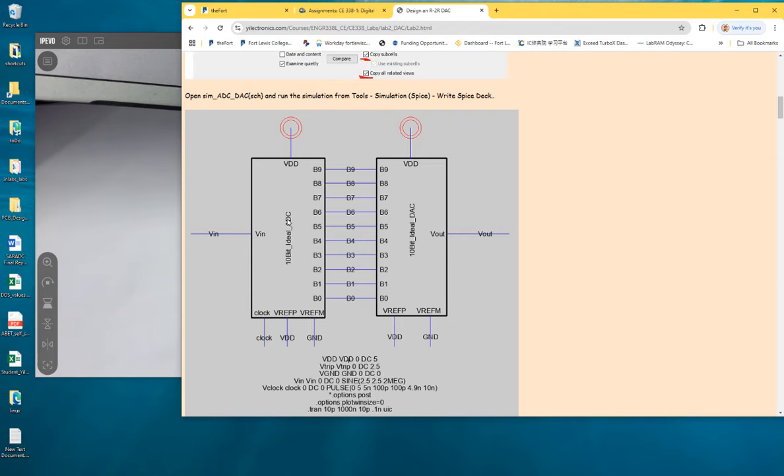You have been using some of the Arduino kits, right? So all the A0 to A5 ports, A means analog. So these are taking analog signals and digitizing them and putting all the digital data into the memory. So ADCs are the front end digitizers that digitize all the analog signals. And so you can imagine that the ADC's output will be digital signals. Digital signal will be multiple bits. You can see this one has 10 bits. And being connected to another 10 bits for the DAC.